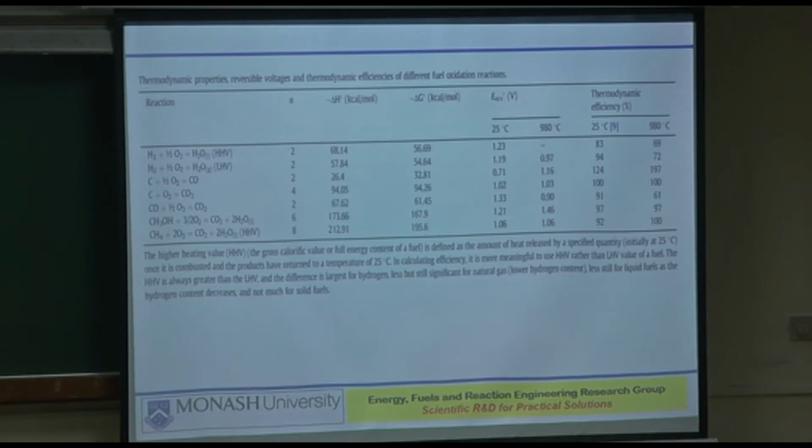And it's quite interesting to see. Well, if you take all the liquids, the water vapor out as the condensate, then you are recovering its latent heat, and therefore we say that the efficiency is expressed on the basis of the higher heating value. But if you allow the water vapor, which is the product of the fuel cell reaction in this instance, to go in the gas phase, then you are not recovering it. So you say that it's done on the basis of the lower heating value.